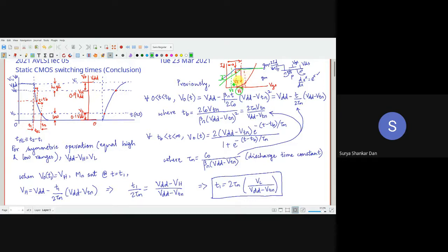Understood? In our next lecture on Thursday, we will finish this off. I wanted to conclude it today. So in our next lecture, we will find out that industry will not go by this exact calculation value. They will also do a very simple trick like this threshold voltage as I have shown you, simply by taking that linear slope. That is not the accurate one. Theoretically, the maximum GM point, this Vt is the correct one.